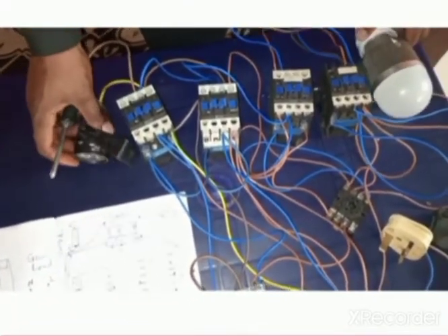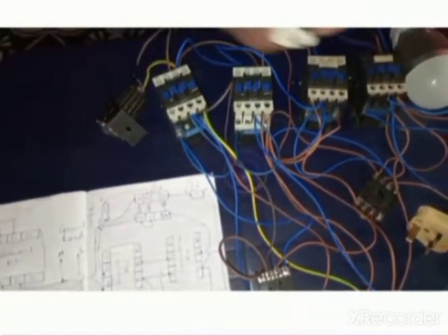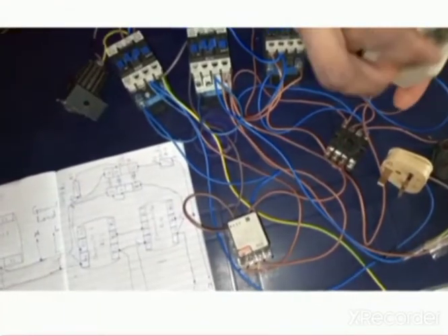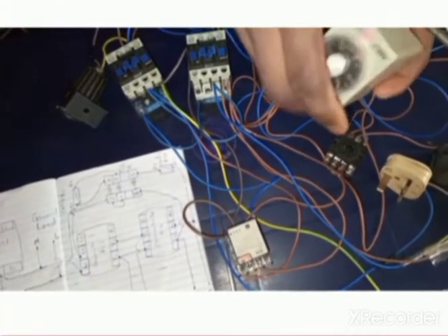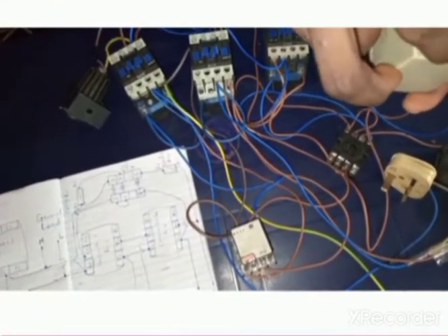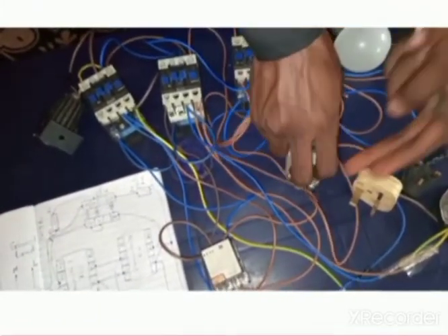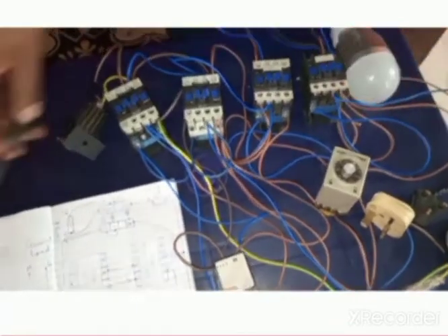Alright, so let's go ahead and fix the pin relay. I will put this pin relay, and this timer I will set as 0 so that it can work as a pin relay. If I want a delay before switching, I can set it to any time, but I will set it to 0. So I will insert it here. Now we have to test.